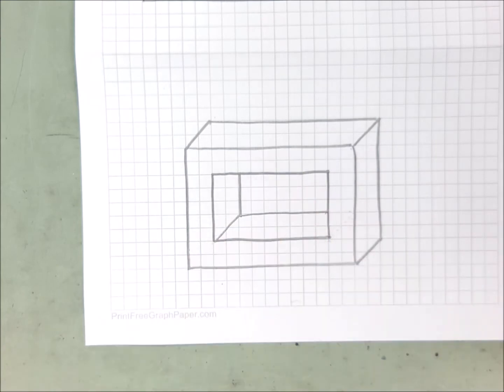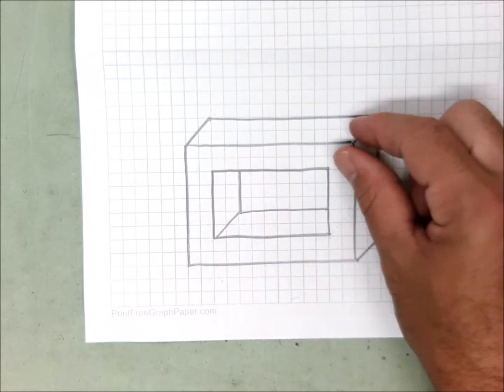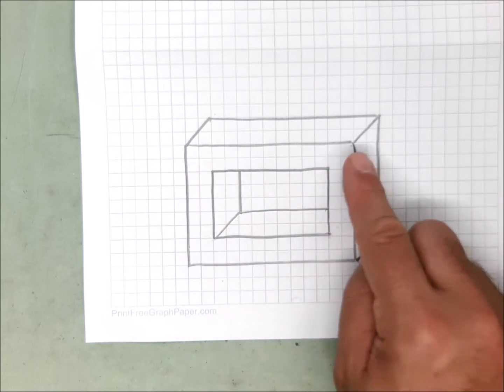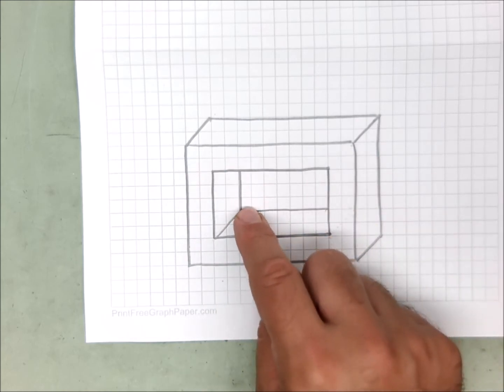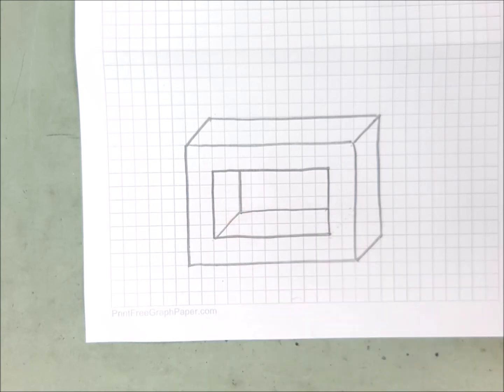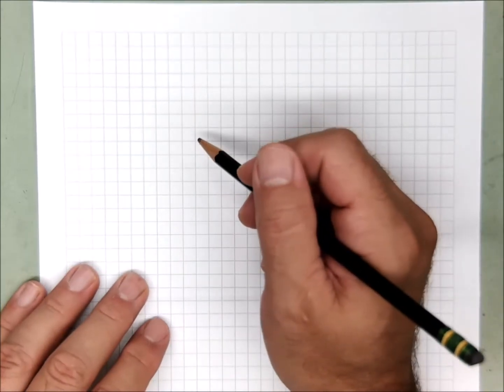So, again, we're interested in what can you see when you make these oblique drawings. This one is a thin piece of material, which means that not only do we see the hole in the front, but we see the back edge of the hole also. The back edge of this square cutout is also visible. Moving on to our next one. Let's take a look at the shape.